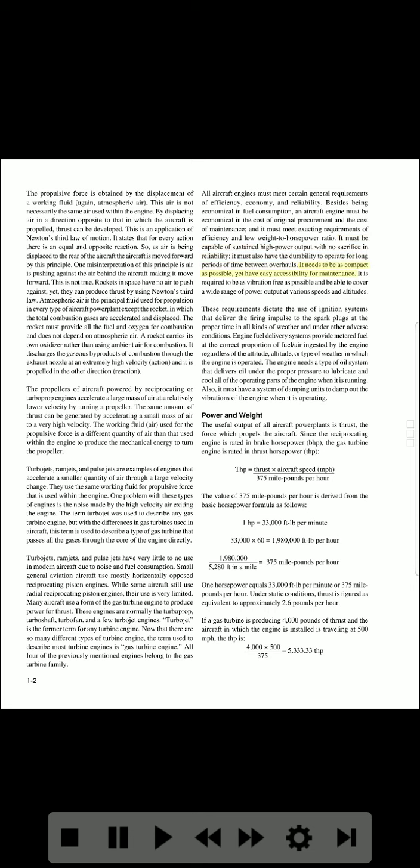It needs to be as compact as possible, yet have easy accessibility for maintenance. It is required to be as vibration-free as possible, and be able to cover a wide range of power output at various speeds and altitudes. These requirements dictate the use of ignition systems that deliver the firing impulse to the spark plugs at the proper time in all kinds of weather and under other adverse conditions.